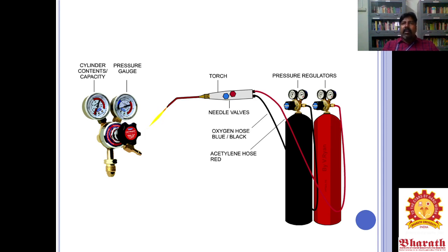So normally we are getting around 3200 degrees centigrade during the welding process, right? And the cost of acetylene is very, very low. That is why we are preferring that one, right? And gases like oxygen and acetylene can be stored at high pressure in separate steel cylinders. This acetylene is very harmful, so we should take a little care to handle the gases, right?